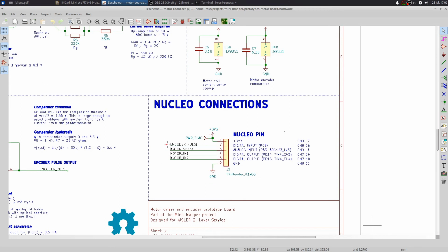First of all, we have the photo encoder pulse, which goes to the microcontroller, and we'll want to be able to count those, so we'll want to run an interrupt off the pin that's connected to, possibly also a timer capture to measure the intervals between the pulses precisely. For the moment, I've just connected it to this GPIO, which is on pin PG3 on the microcontroller.